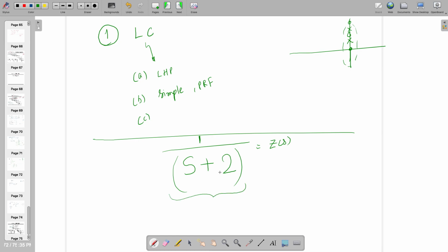But here you can see that the root of these poles is only -2. It has a real part also. So whenever you have a real part, it signifies that you are going to have a resistive element, right? But if you have something like this, then it's plus or minus j root 2. So this entry is coming exactly on the j omega axis, which gives us information that this entry will be LC. Right? So I am going to synthesize using LC.